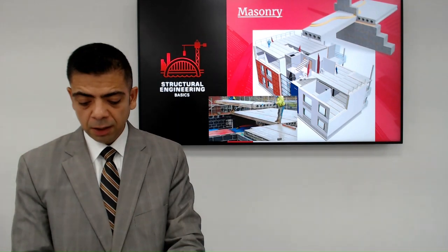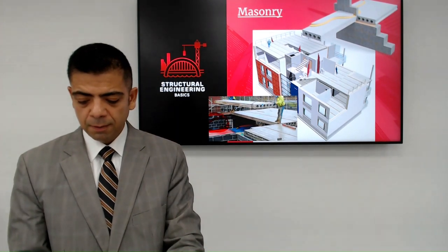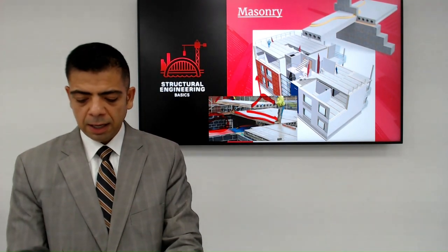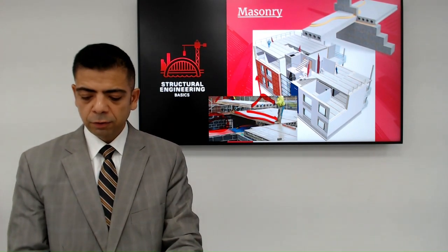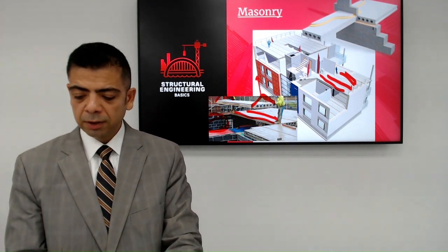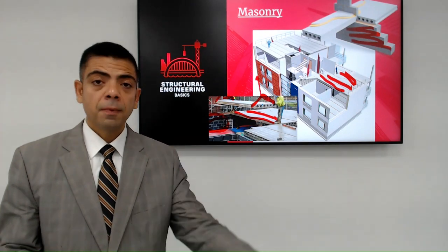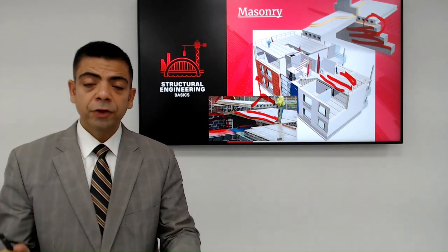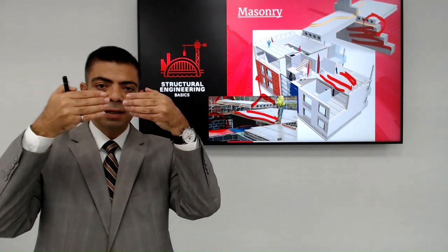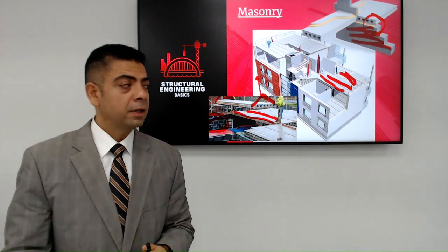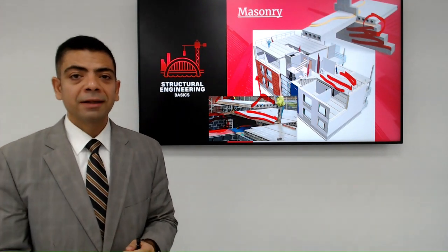You can see here, this is the masonry, these are hollow cores, and you will need the crane. You can see the chains, and all you have to do is put the hollow core, start building the next floor walls, and then detail the connection to leave bearing spaces for the hollow core, and then repeat the cycle. So the floors can go up relatively quickly.